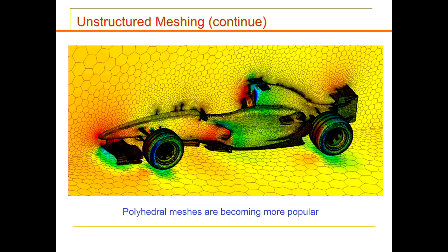Okay? Now, the polyhedral feature is in Fluent, but it's not in CFX. What Fluent does is that it takes a triangular mesh and combines 6 triangular elements into a polyhedral one. So you can see that from one polyhedral element, you already have a reduction of 6. So basically it takes the 6 triangles and reduces them. You can just imagine that a triangular mesh can be reduced using a polyhedral mesh.